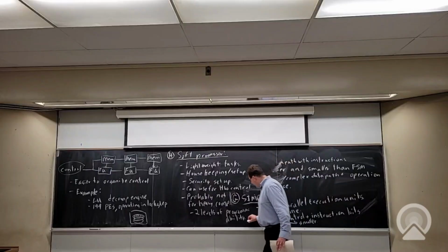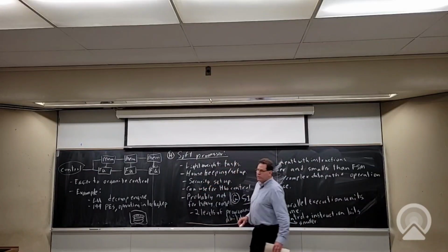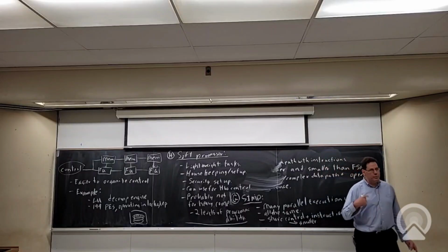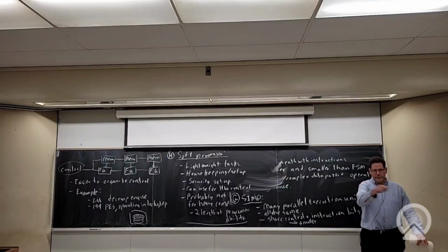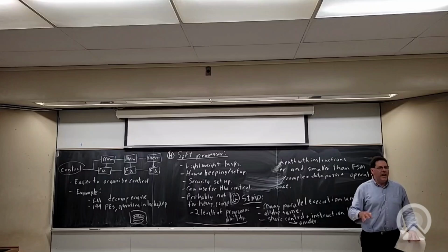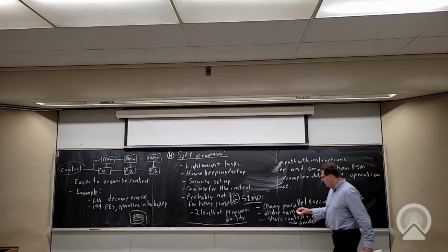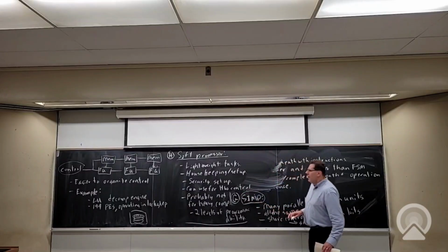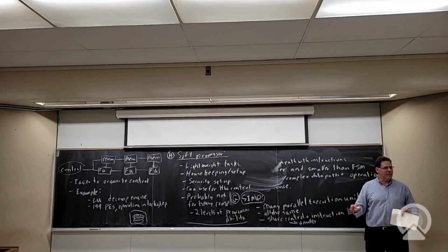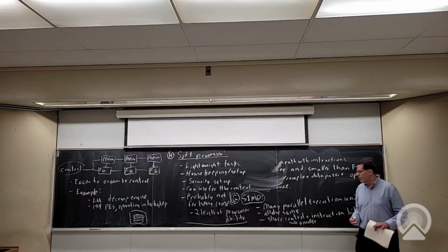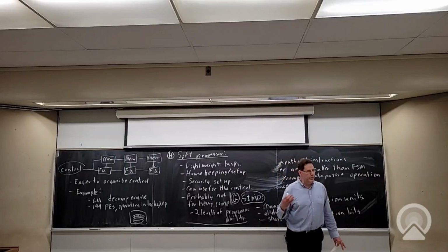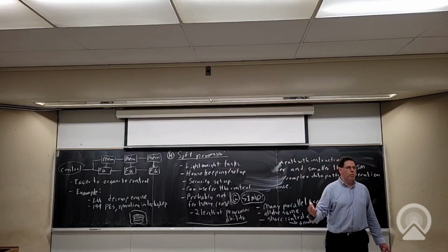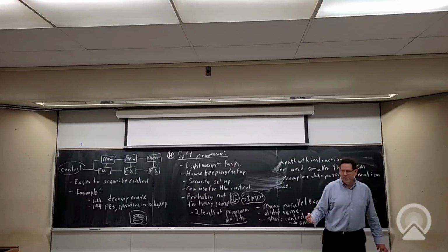And now a processor also loses a huge amount of performance, because instead of just doing something, it basically has an instruction word that says, configure all these muxes in the following way, and do this one or maybe a few things, maybe even more than a few with SIMD. But I basically have a data path that has more muxing than I normally need, and I have to decode this instruction to say how to configure the data path for every operation. That's what one of the papers you're reading this week talks about, and that's also a very large cost, like an order of magnitude or more in efficiency.